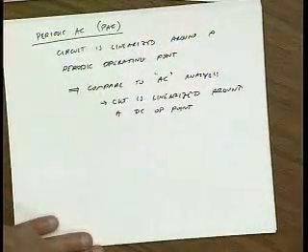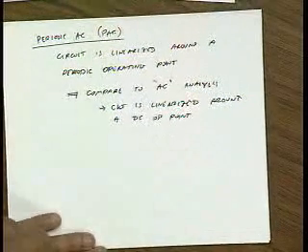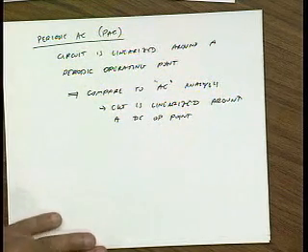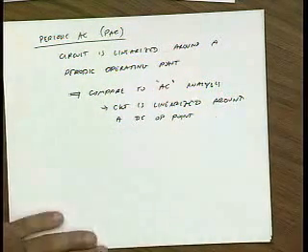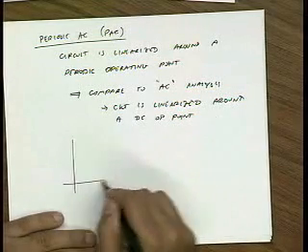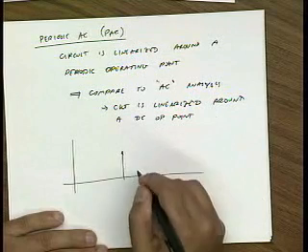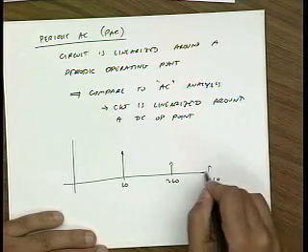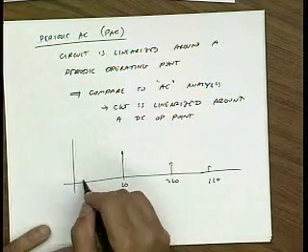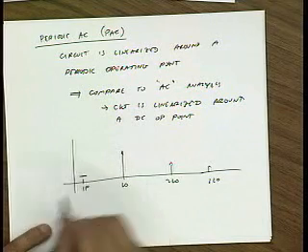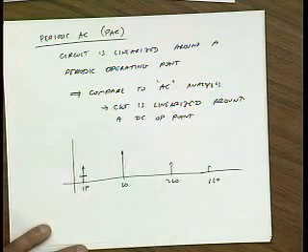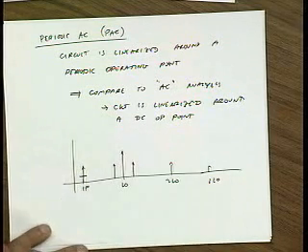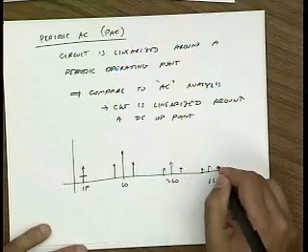Now, what's complicated about PAC is, what does a transfer function mean, right? In fact, you can see that in periodic AC there are as many transfer functions as there are harmonics in your signal. Again, a simple mixer is a great example. Here's my LO, here's my 2LO, my 3LO. Let's say I apply a signal at IF, and it's an upconversion mixer. Well, I know that this can mix to these sidebands, and these sidebands, and these sidebands.